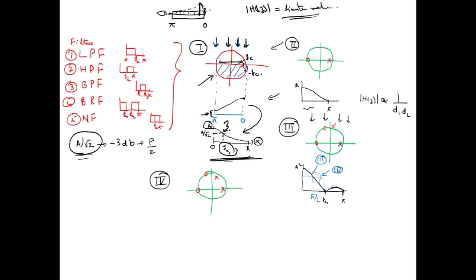If you are working with very low amplitude signals, it may create some problem during the analysis. Okay, now due to this reason, we basically want to stop the frequency component at pi. Okay, we want that at pi the frequency should be completely suppressed. Okay, so to achieve that, look over here, we have just placed a 0 at pi.